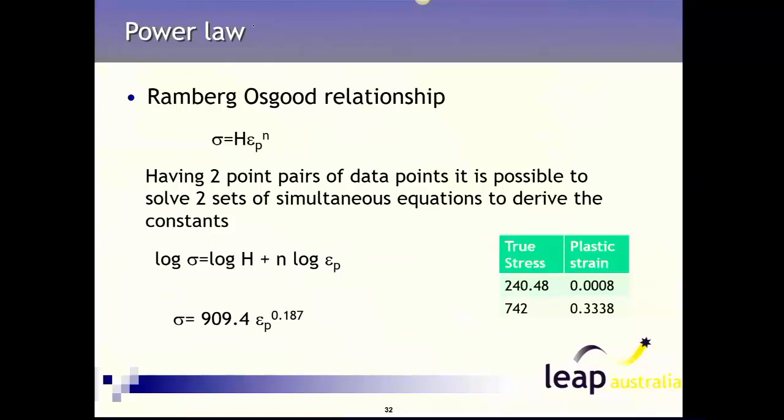Okay, so if you want to, you can use those two data pairs to build a power law relationship, and then from this power law relationship you can build a multilinear stress strain curve. This is probably a little bit of overkill, but it is just to show that if you had tensile test data, you could do a power law fit to your data, or a linear fit to a log-log plot of your true stress, true strain, to come up with a better representation of the material properties.